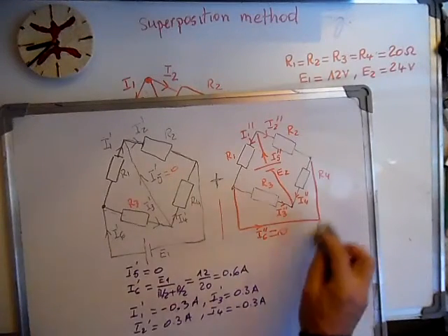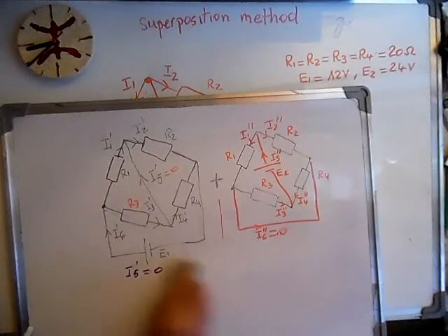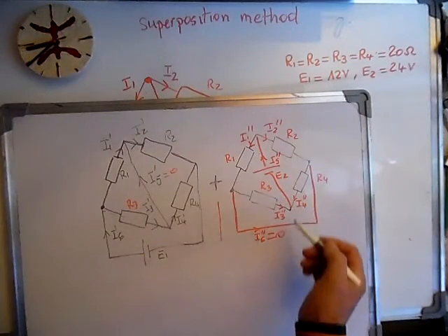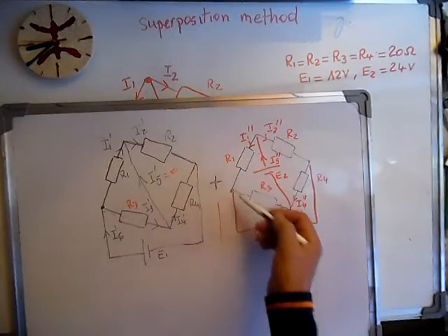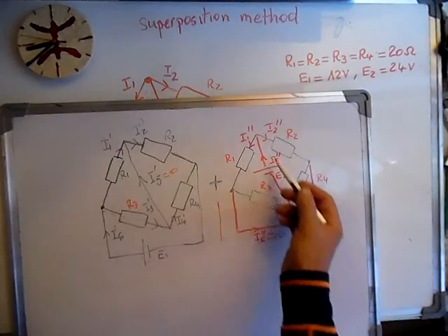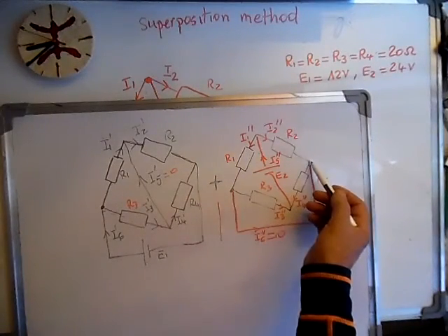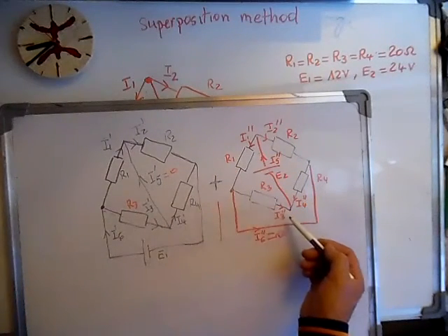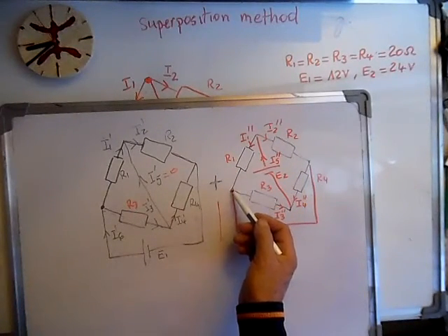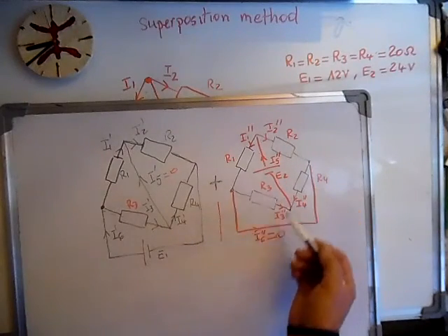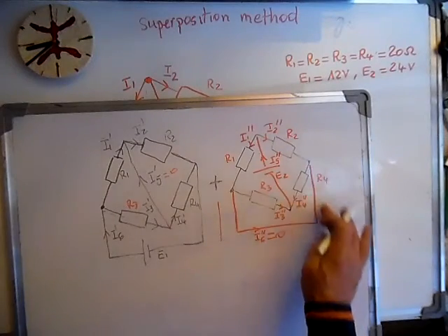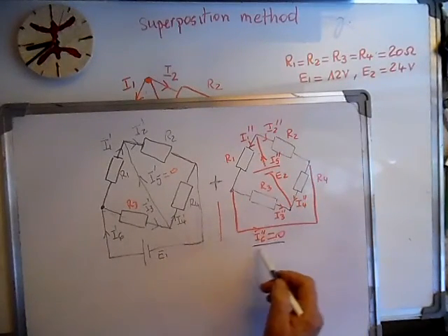I think in the other circuit we take E2 on. So here it's the same thing. This point has the same potential because this is a voltage divider. The voltages at this point and this point are equal, so this connection doesn't exist, which means the current is 0.